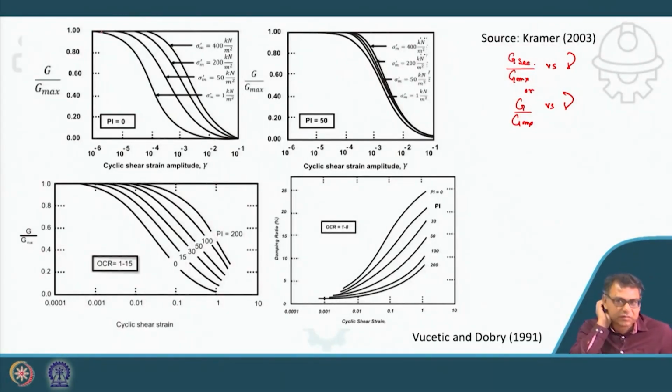And I have given what is low strain level. So generally if you look at this curve, this strain level varies from 10 to the minus 6 to 10 to the minus 1. So in percentage it varies from 10 to the power minus 4 percent to 10 percent. You can see 10 to the power 1 means it is 10 percent, and it is actually 10 to the minus 6 to 10 to the minus 1. So that is the general range, but this damping is giving 1%.